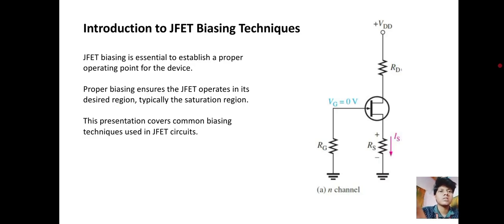First, introduction to JFET biasing techniques. JFET biasing is essential to establish a proper operating point for the device. Proper biasing ensures the JFET operates in its desired region, typically the saturation region. This presentation covers common biasing techniques used for JFETs.